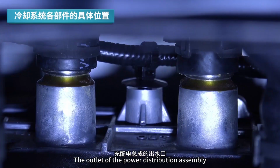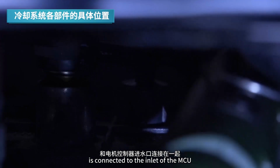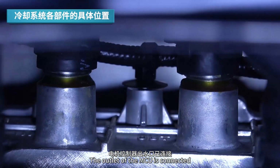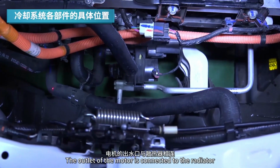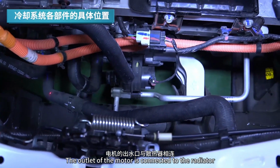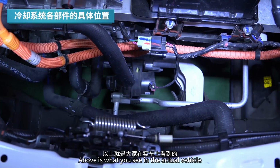The outlet of the power distribution assembly is connected to the inlet of the MCU. The outlet of the MCU is connected to the inlet of the motor. The outlet of the motor is connected to the radiator, forming a circulating loop. Above is what you see in the actual vehicle.